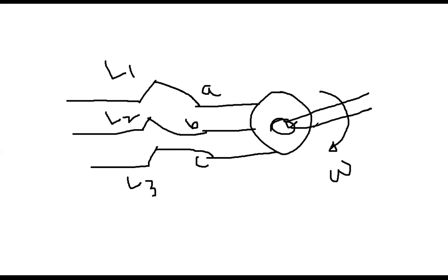And then at first you notice that the motor has started rotating in the opposite direction. This is the indication that the phase sequence has not been matched. Phase sequence is different. But if you see that after making this connection, it is properly rotating in the suggested or recommended direction, then it is fine. It properly matched. If you see that it is rotating in the opposite direction, then immediately you stop the motor. For example, you disconnect all the connections, and then the motor will be stopped.